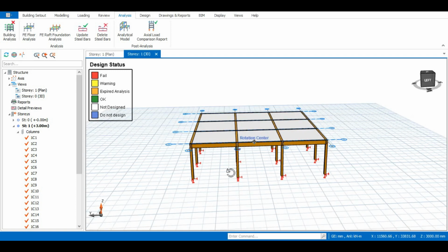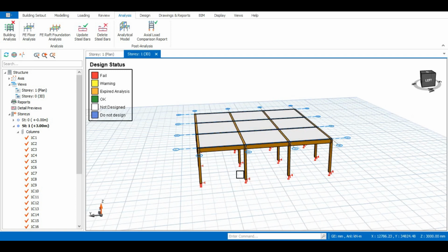Today, we'll be learning in Protastructure how to design a strip foundation. However, a strip foundation can be reinforced and can be unreinforced. For the case of an unreinforced strip foundation, it's usually done in combination with other forms of foundation such as pad foundation, which is very common where I come from, as we incorporate a layer of concrete in our pad foundation on the surfaces that will be laying the masonry work in order to give the foundation masonry work a very solid ground to stand upon.